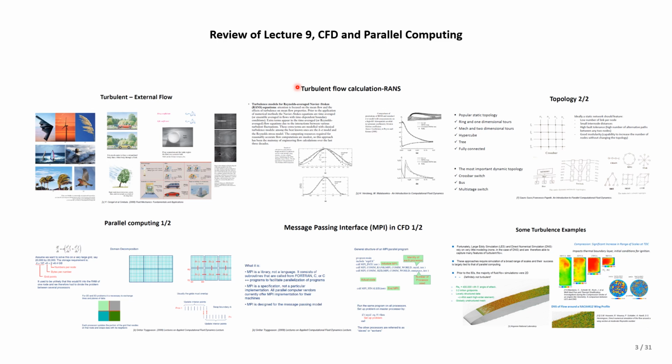However, it's very costly, and it is not common to use it for industry applications. Therefore, to have a numerical solution for turbulent flow, especially with LES and RANS, we need parallel computing. We had a few examples, and we saw in some studies RANS could not provide the required solution, and we had to use LES and DNS, so high performance computing is essential.